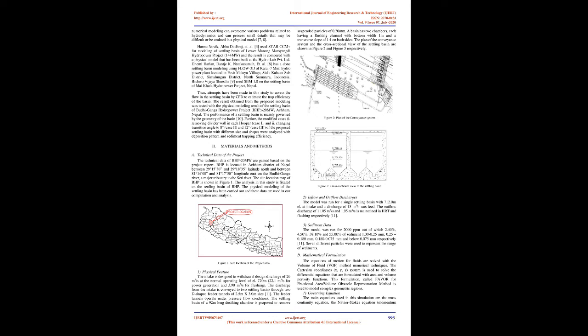Owing to the complicated nature of flow dynamics of water, the functioning of headworks and settling basin is examined by physical modeling and numerical modeling. Physical modeling is developing a scaled physical model based on a similarity theory, whereas numerical modeling is the process of appropriately developing a mathematical model/replica for a complex physical reality that enhances engineering judgment with the power of the digital computer. 5. The physical model test is costly as well as time-consuming, and on the other hand, numerical modeling has certain advantages over physical modeling such as scale effect, cost, time, and interpretation.